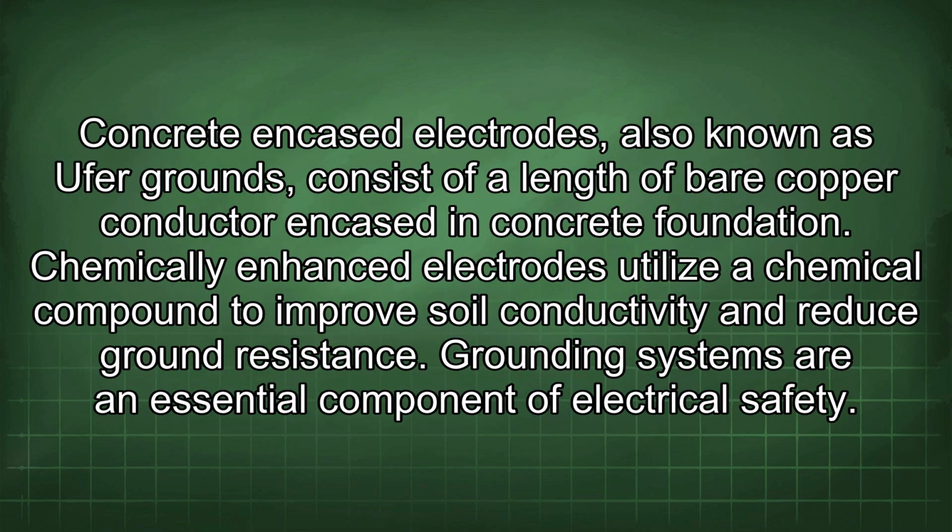Concrete-encased electrodes, also known as UFER grounds, consist of a length of bare copper conductor encased in concrete foundation. Chemically enhanced electrodes utilize a chemical compound to improve soil conductivity and reduce ground resistance.